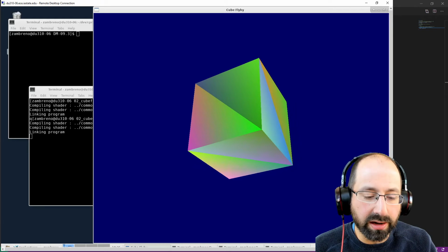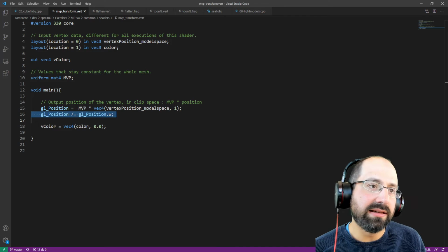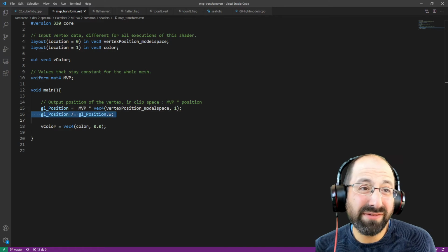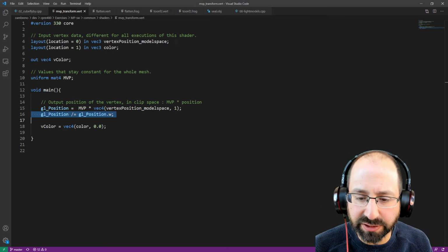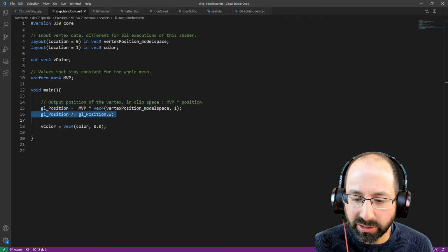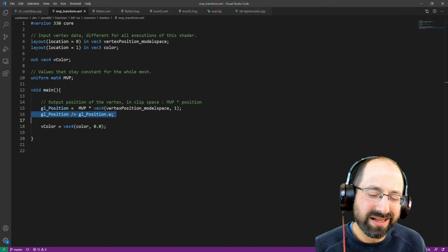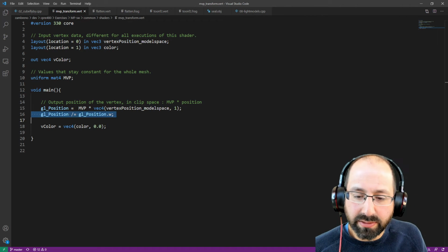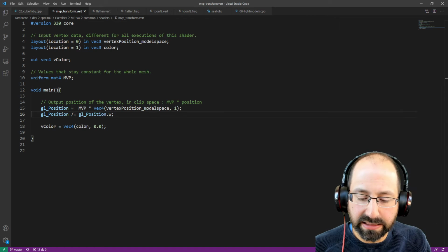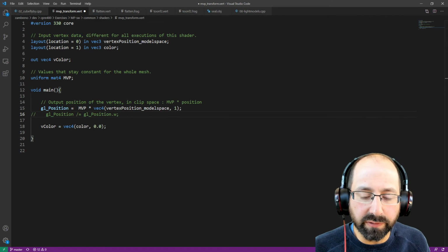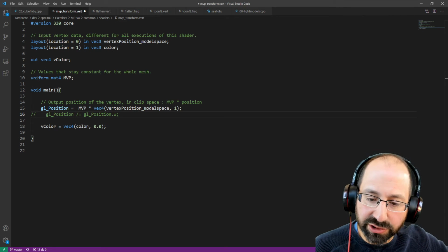fixed function hardware. But again, what I'm leaving as an open question is we already have these shader cores that can do division and do division relatively efficiently, maybe more efficiently than our division that we're having to kind of compromise given our lack of space on chip for it. Why not do this, right? I'm not specifying it, and it's definitely not a requirement that we specify this as part of the shader itself. That's definitely never a requirement you do that yourself in the shader.